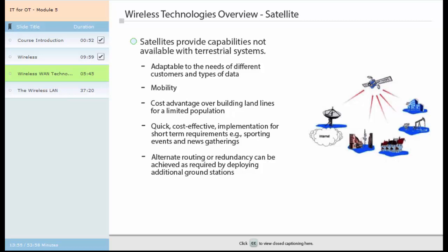They also offer great versatility in implementation for paging, voice, data, and video. Since satellites are based in orbit around the Earth, cost of bandwidth and use is independent of distance on the ground, making these systems especially attractive for long-haul communications. And with a satellite out in orbit over the Earth, there are no geographical obstructions that prohibit communications as there are with landlines. However, given the distance that the signal has to travel to reach the satellite and then return to a receiving station on the ground, transmission delay is always a significant drawback for satellite communications.